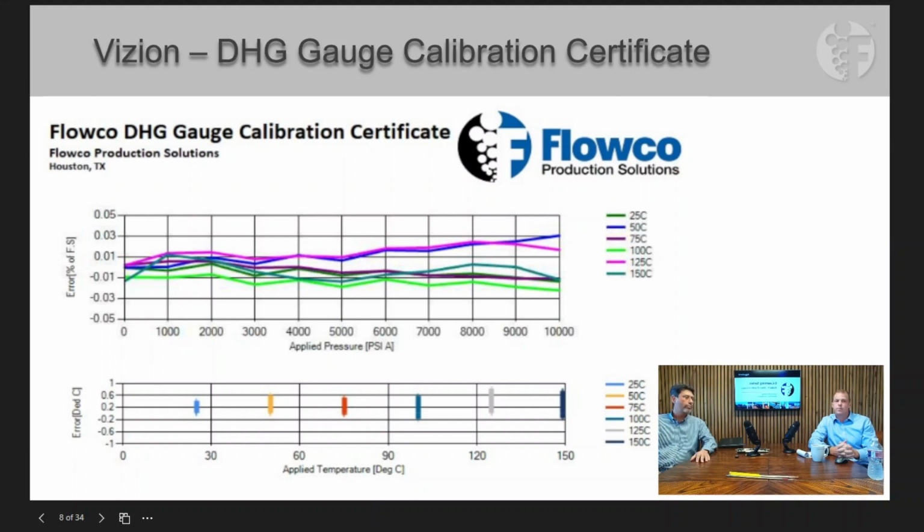You can also monitor downhole flowing pressure on a gas lift installation, either tubing flow or annular flow. And you can also measure pump intake and discharge pressure on a jet pump or a hydraulic pump. Correct. Those are typically the applications we see, with some form of artificial lift.